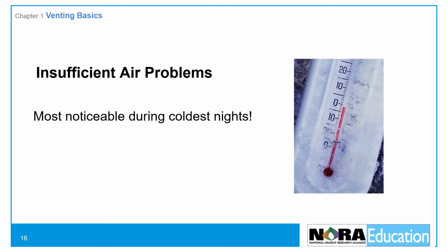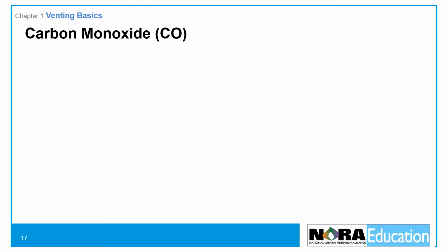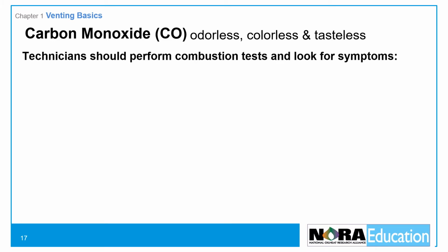Insufficient air problems are most noticeable on the coldest nights when the heat loss is the greatest and the windows and doors are closed for extended periods of time. These conditions can lead to incomplete combustion and the creation of carbon monoxide inside the combustion chamber and vent system. Carbon monoxide is odorless, colorless, and tasteless. Therefore, in order to detect its presence, technicians should perform combustion tests anytime fuel or combustion air has been dealt with,